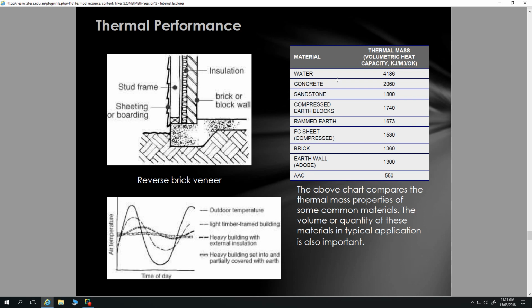Unless we use things like surplus cement. There are the giant concrete blocks you get, from people who do casting, with all the remains of their concrete; they just chuck it into these forms to produce large concrete blocks. Has anybody seen any of those about the place? Yeah, a few nods on those. So that's a form of huge amount of thermal mass there, but it's essentially a recyclable or waste product